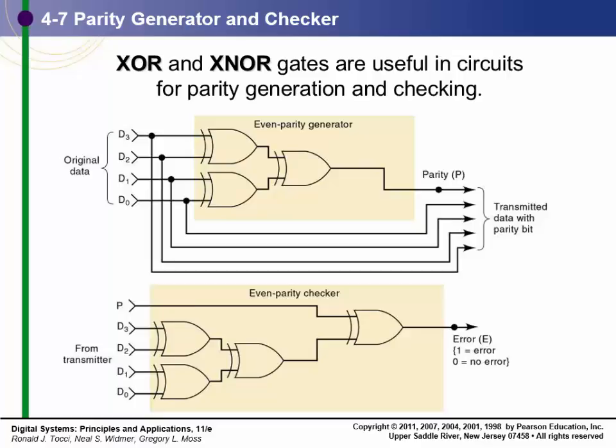And the reason is that it may reduce the number of gates, but if you've got 2 million NOR gates on an IC, what difference does it make? As soon as you start putting a different type of gate into the circuit, you've complicated things. So it's easier to implement something with a gate array with nothing but one type of gate on it than to play around with multiple types of gates. So that's why the XOR and the XNOR have some very useful properties when we look at understanding some circuits, but in implementation, you just don't see them that much anymore.